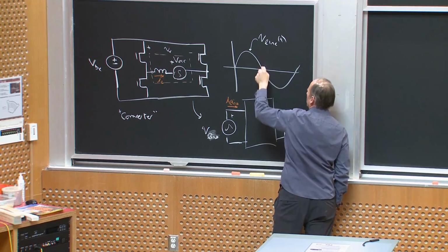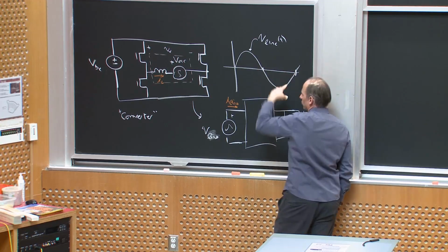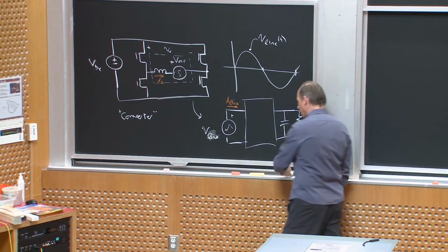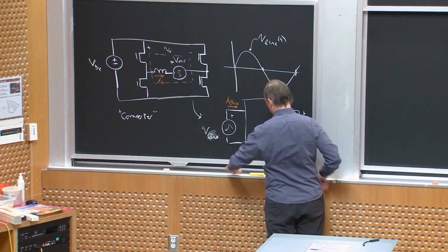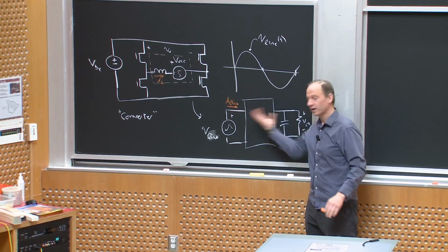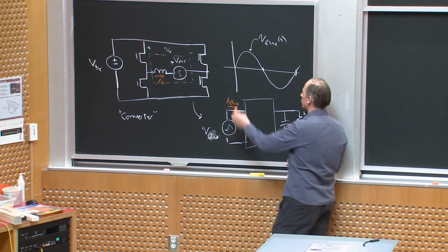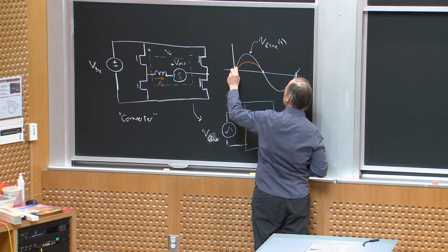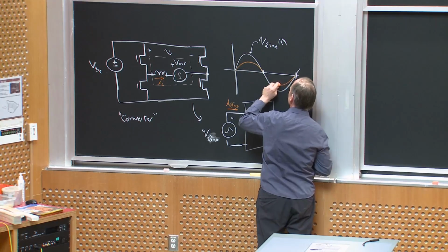Right, this is the line frequency. This is, you know, 120 hertz, 60 hertz or 50 hertz, depending upon where you are, right? The best I can do in terms of power factor is to make my whole converter look like a resistor, right? So my goal might be to have a current waveform that looked just like this, okay?